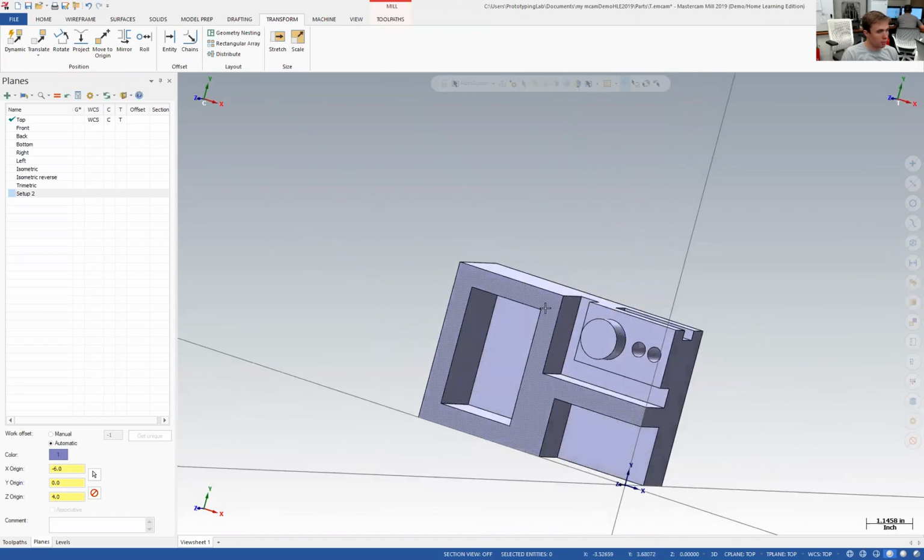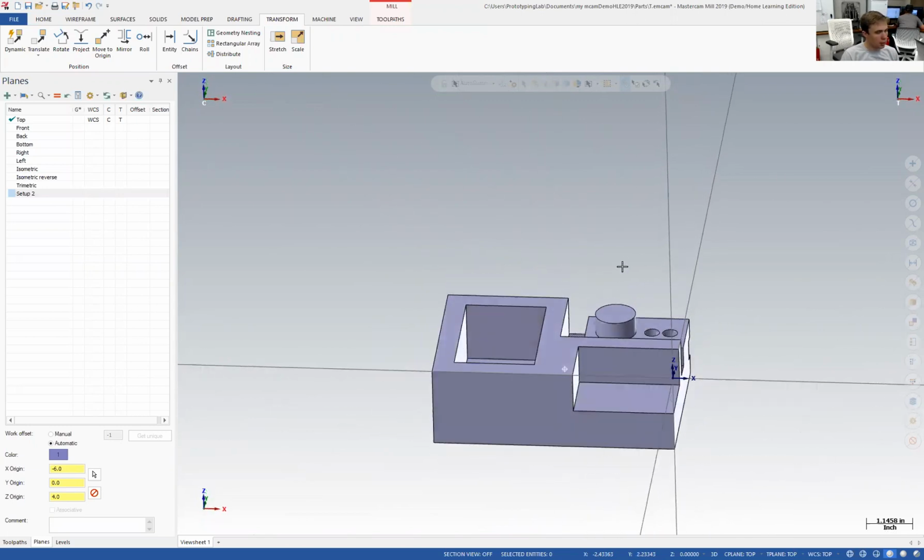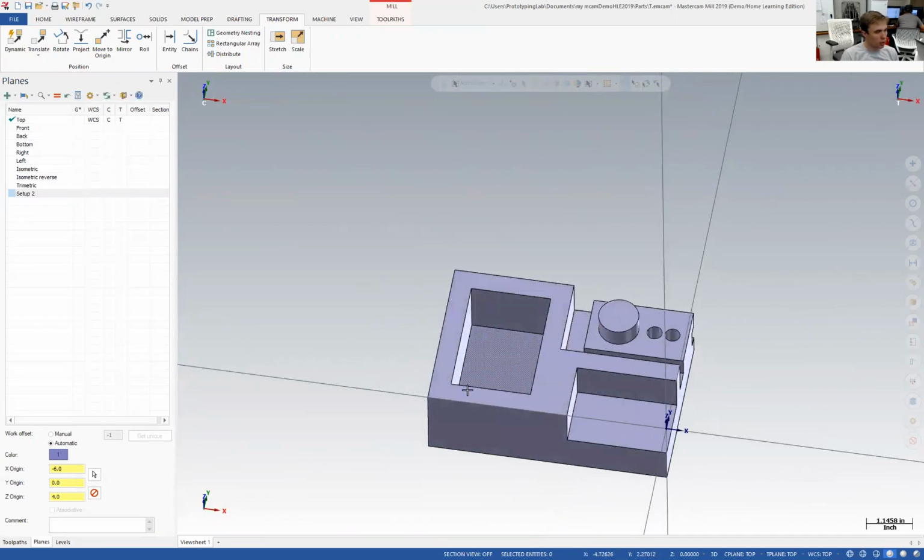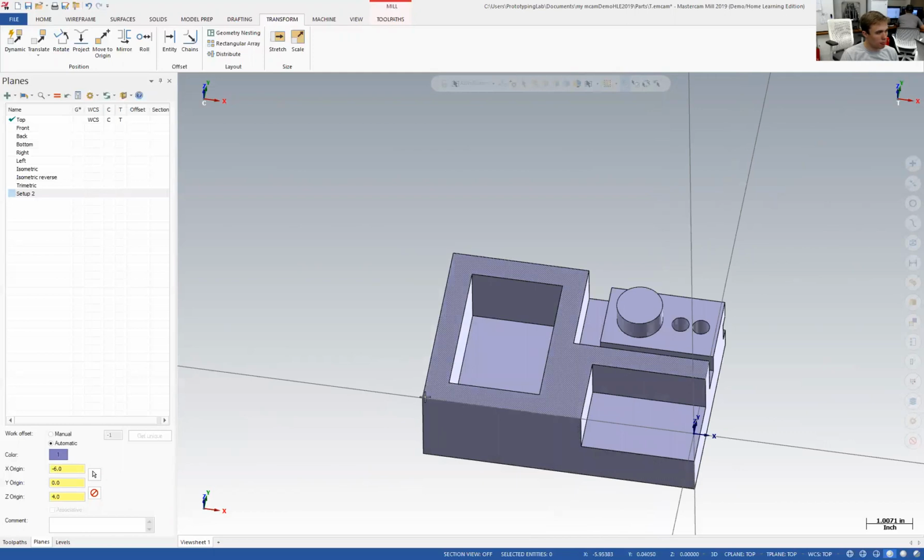They do share this top plane. So we know that I can probe this surface for this datum, and then I can probe this surface again for setup 2, which is right here. You want to be able to probe the same physical location on your part for each datum as often as possible. So probably there's lots of good options, but one of the good options would be to use this corner